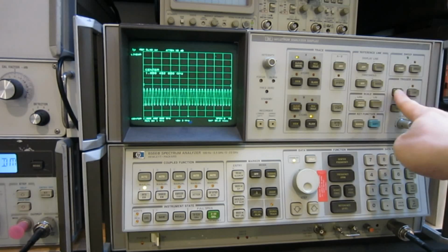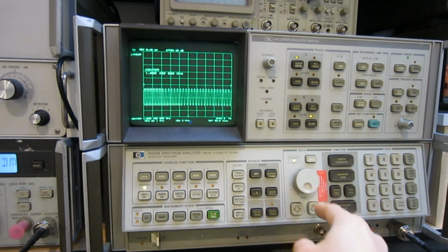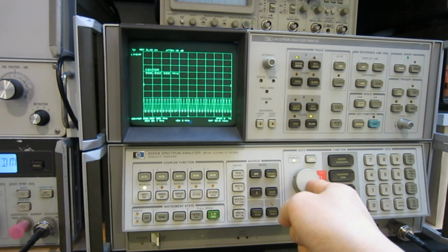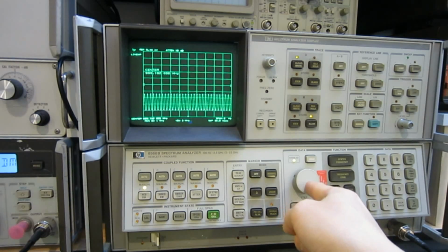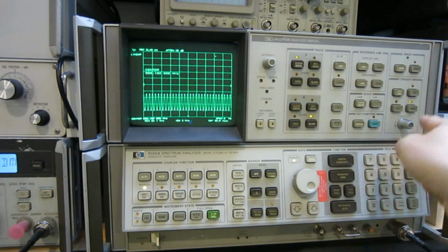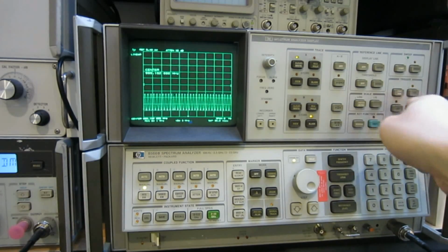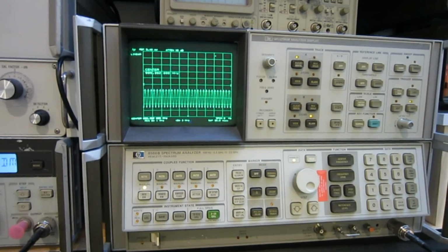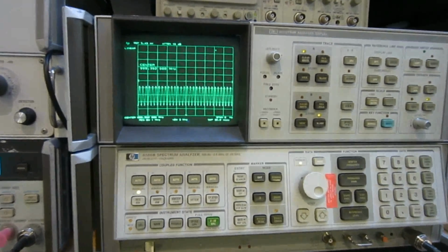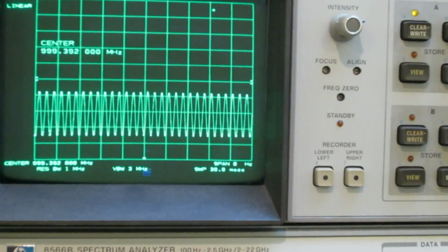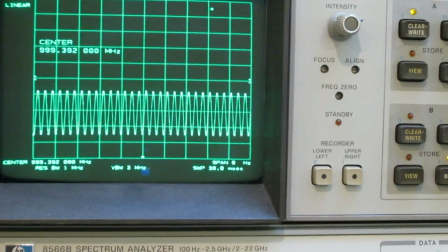Equally, we can do that for our lower band as well. So if I just lower my center frequency, if you lower too much, yeah, so lower to 999. So here you can see that once again. Well, I can probably do that a little better, like now. Yep. So now you can see that this trigger signal also looks pretty good. So this is our demodulated signal at the lower band.